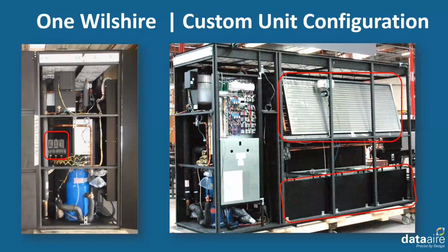Here is the water regulating valve. Normally we have one water regulating valve, but in this unit, to save space and reduce pressure drop, we use 3 valves in parallel. And this is the water-cooled, variable speed scroll with variable frequency drive. That shiny box above the compressor is the drive. And here's the hinged electrical panel that swings out of the way so that only front access is required for service and maintenance.